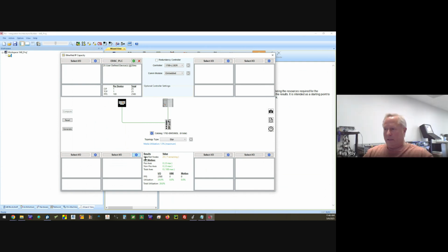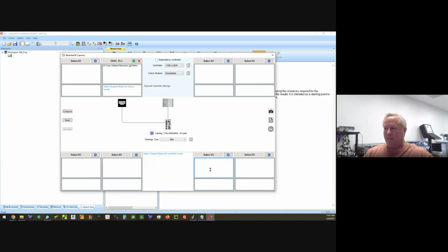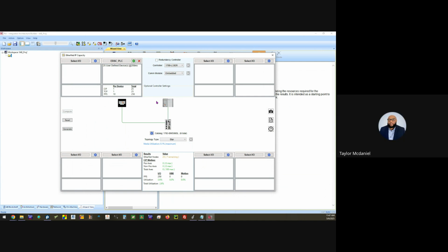And so like here it says utilization 26%. Well, if I crank up the RPI rate and compute, now it's 2.6% because I'm not pounding it as hard and as often. So just by changing the RPI rate changes the load on the processor.